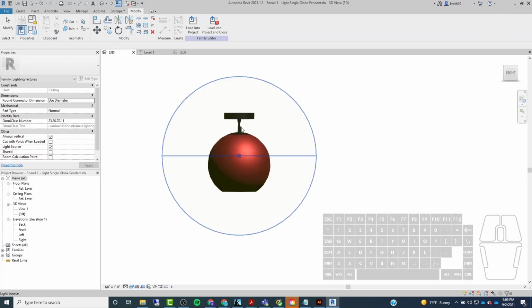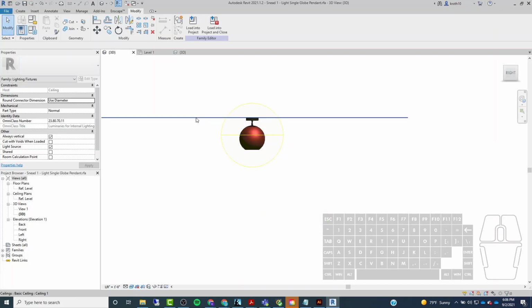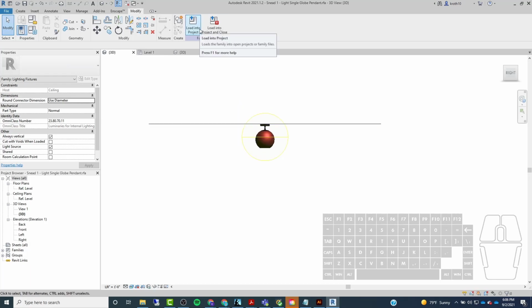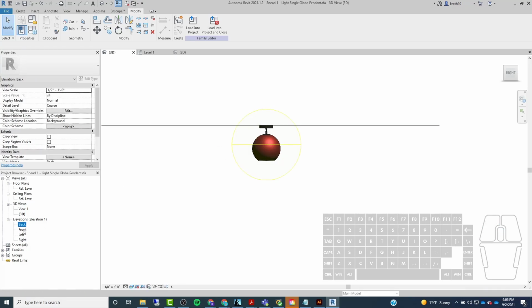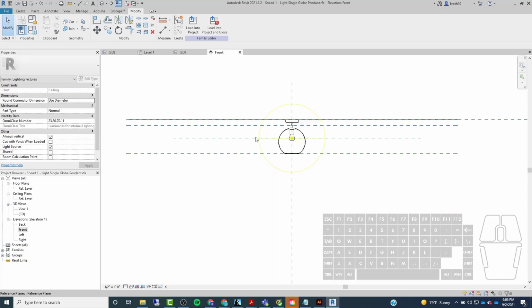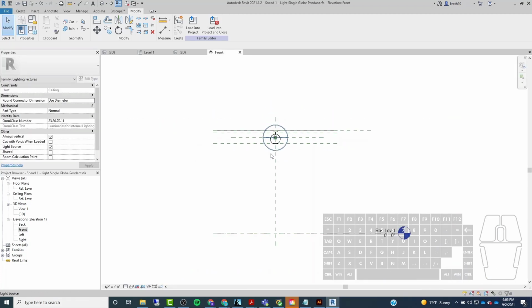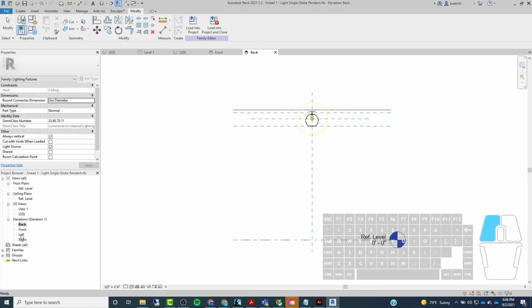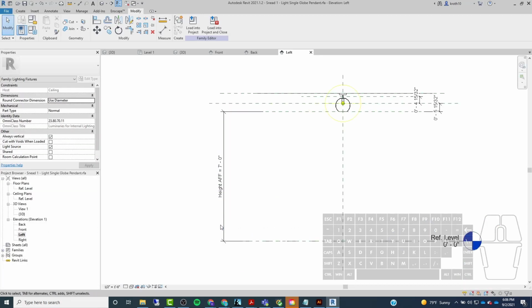It looks bad in this instance right here because of where it's set to, but yeah, you could set it to a higher dimension. What you'd really want to do, the better way to control those, is to control the distance that it's being suspended from the ceiling like I had originally, instead of it being controlled by the height above the floor. It's better to control the distance that this drops down from the ceiling. But you can do it either way.